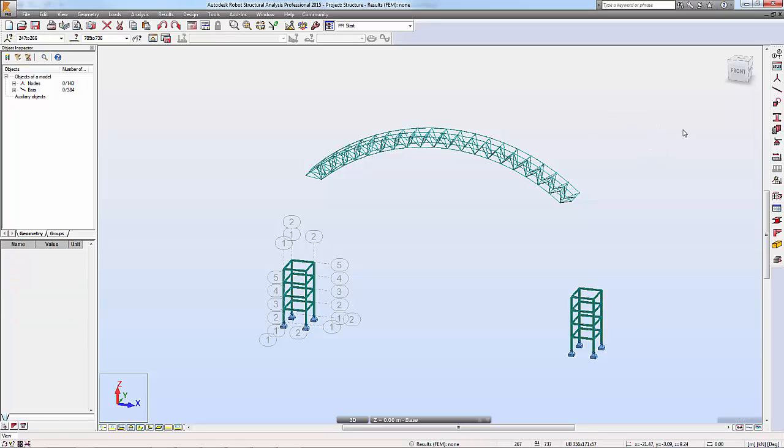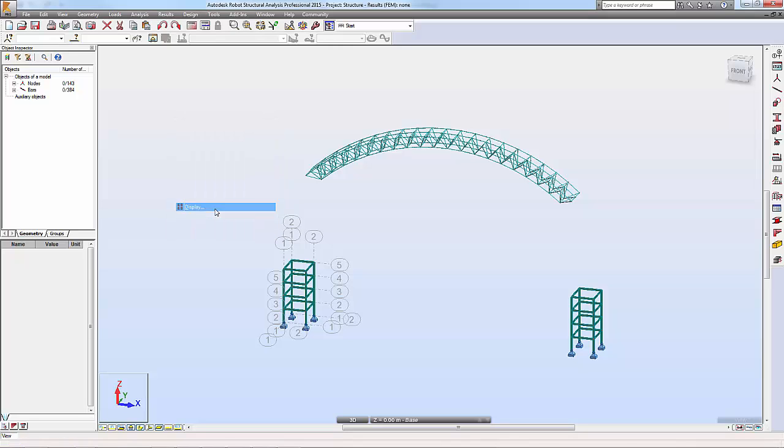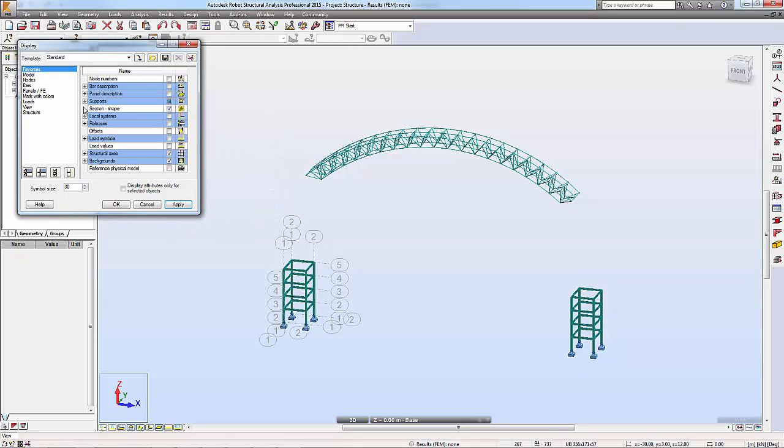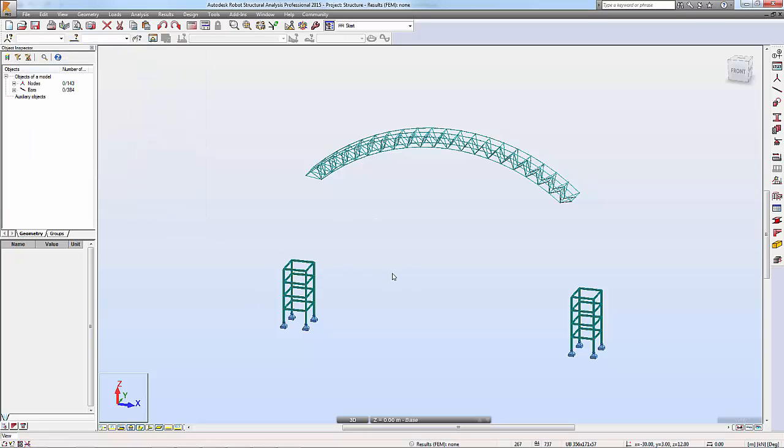So let's click on wipe area, so that deselect all the things. Then after that, let me see how can I change the view of the display here. So let's maybe change the local system, local system grid line, and this is a 3D view, yes, but when the structural axis, so let's untick this one, the structural axis, and then click on apply. So this one going to disappear, so make it easy for you to view.